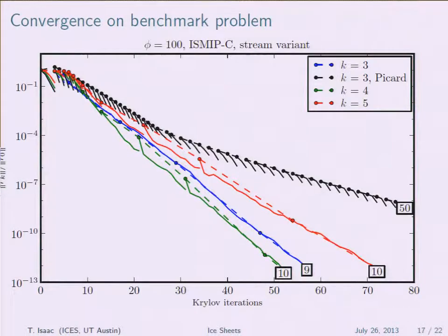And so for our nonlinear solver, the outer Newton iterations we can do in about 9 or 10, and the polynomial order of our approximation doesn't really affect things. And then if we use Picard, which is kind of like that near analytical gradient that you heard about in the previous talk, you would have to have 50 outer iterations and have much worse convergence.